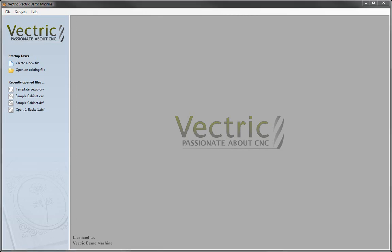So now what we want to do is load in a different cabinet design that's based on the same setup as our template and apply our template to that new data so that we can automatically generate the toolpaths for it. Now typically cabinet design programs will save a whole bunch of separate DXF files. That may be for each cabinet, or it may even be for each component within the cabinet.